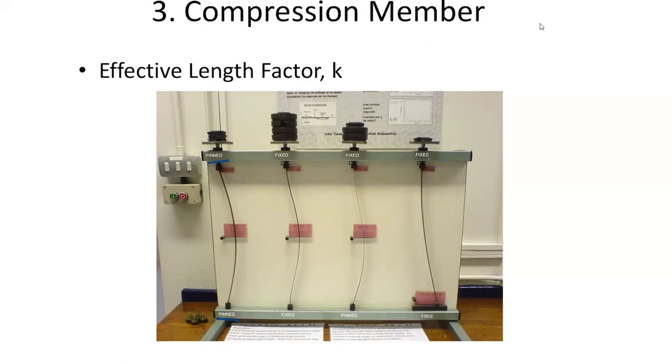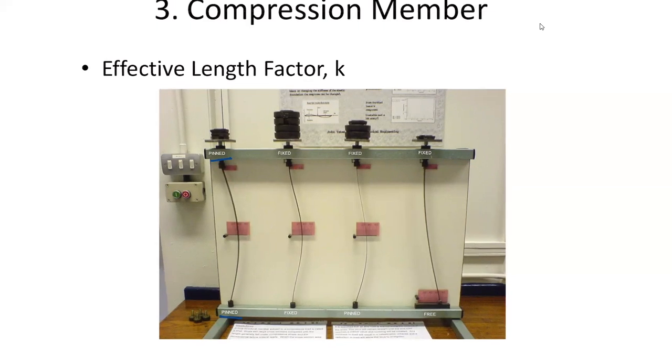And if you can recall the formula that you developed in the mechanics of materials class, it's based on one perfect design curve. So you can say that K for this case is equal to 1. Now, when you fix both like this, notice that it carries more load. When you fix, the rotation here becomes 0. So the sine curve is only half of the length of the member.